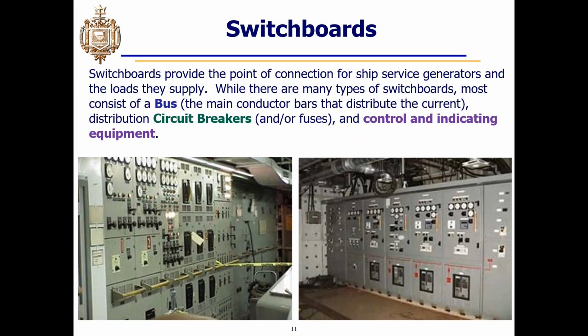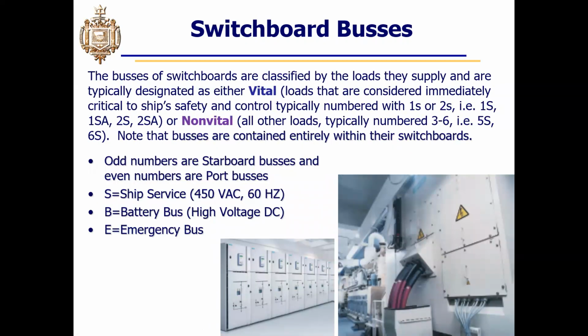Many of these circuit breakers could be remotely operated. So they'll have little dead front fuses on the outside, which will supply power to whatever servo is controlling the circuit breaker, whatever magnet is controlling the circuit breaker, and also to whatever remote control switch is remotely actuating it. You can see these particular switchboards also have meters for monitoring the loads and monitoring incoming sources, but the makeup and construction of your switchboard is ultimately going to be dependent on its purpose. Okay, so what else have we got here?